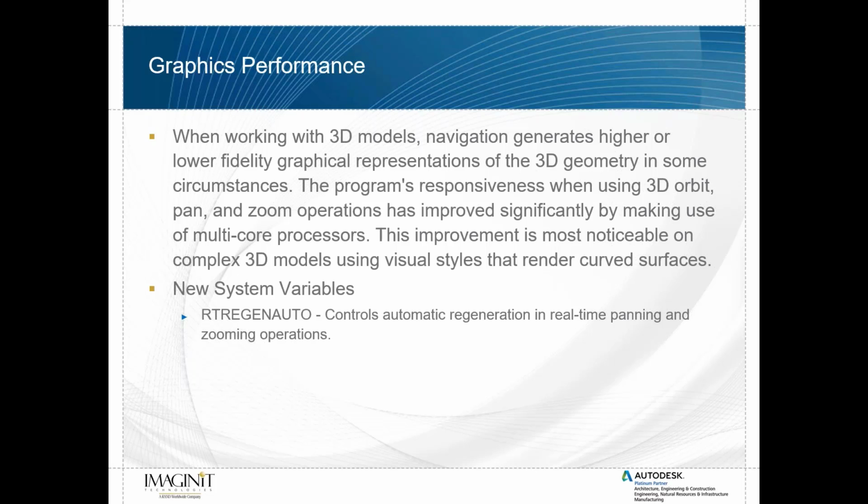So no, the hatch command has not gotten any quicker. It's still the same. Is Drawing Compare only for vector drawings, or can comparison be made for raster files? Nope, for raster files it's just the outside boundary that it picks up. For the hatch command, I prefer not to use the ribbon. I don't like how the ribbon interpolates my hatch, so I change mine to HPDLGMODE. I change it back to 1 so I get the traditional classic hatch pattern box, and I find that is quicker.